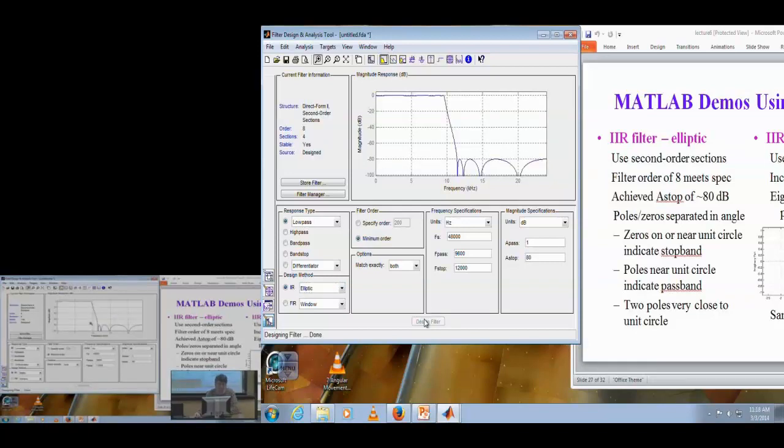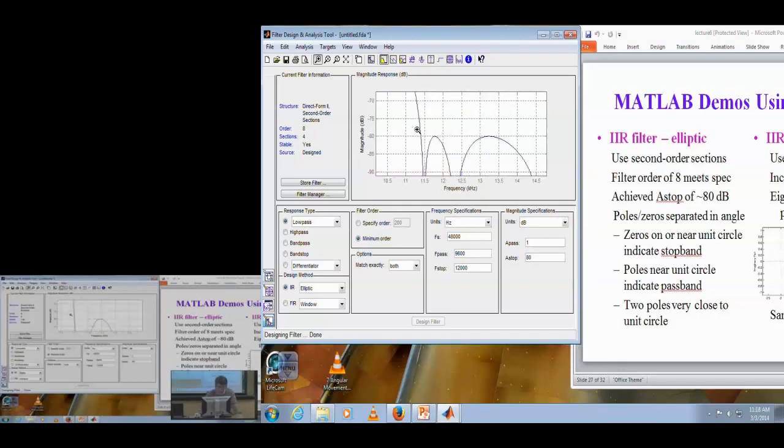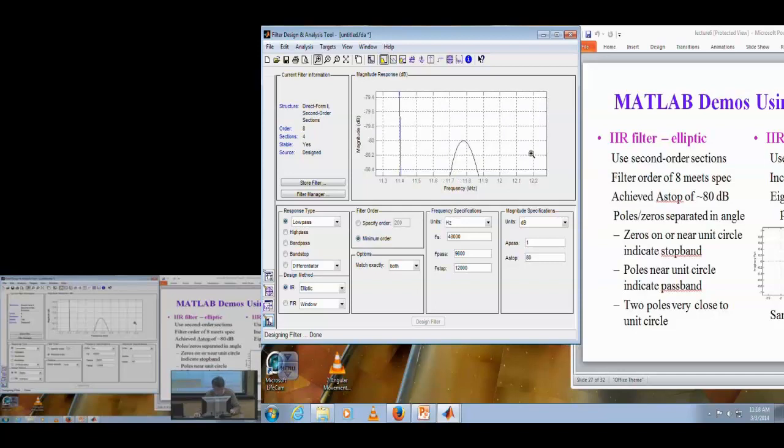Eighth order. Now again, the nice thing with the classical IIR filter designs, Butterworth, Chebyshev, and elliptic, is they are closed form formulas. There's no matrix inverse, there's no iteration. Direct closed form. And the order calculations come from finding roots of a polynomial that's used in those design algorithms. So the filter order is just really accurate. I haven't seen it fail over these years. Okay, so this is eighth order elliptic. Let's see if it meets spec. Yeah, right, dead on. Okay, so dead on.